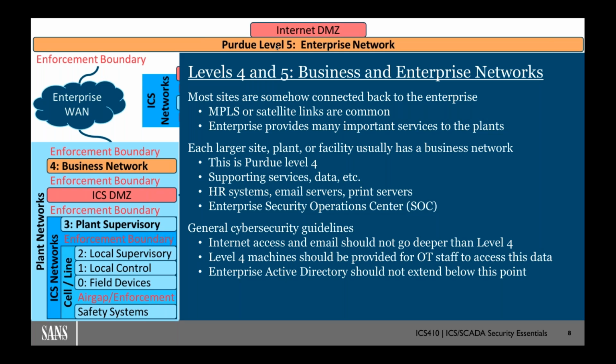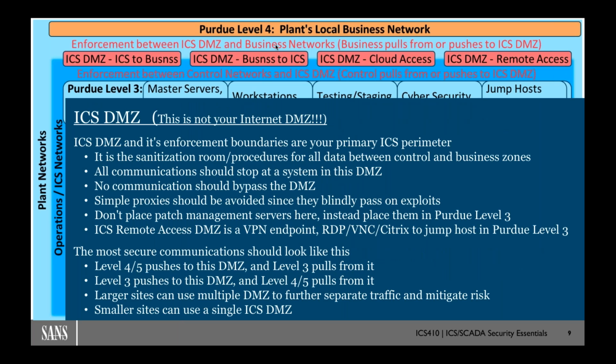Even if you have machines that need Active Directory inside of your control network, we should not share Active Directory with the enterprise. If we do, that tends to leak all of our control credentials into the enterprise and creates a trust boundary that attackers can exploit to get into the control network. You do not want to have an attacker that compromises the enterprise Active Directory, which does actually occur quite frequently. We don't want those attackers to immediately, automatically have access to the control networks, right? Isolation. So let's go a step lower.